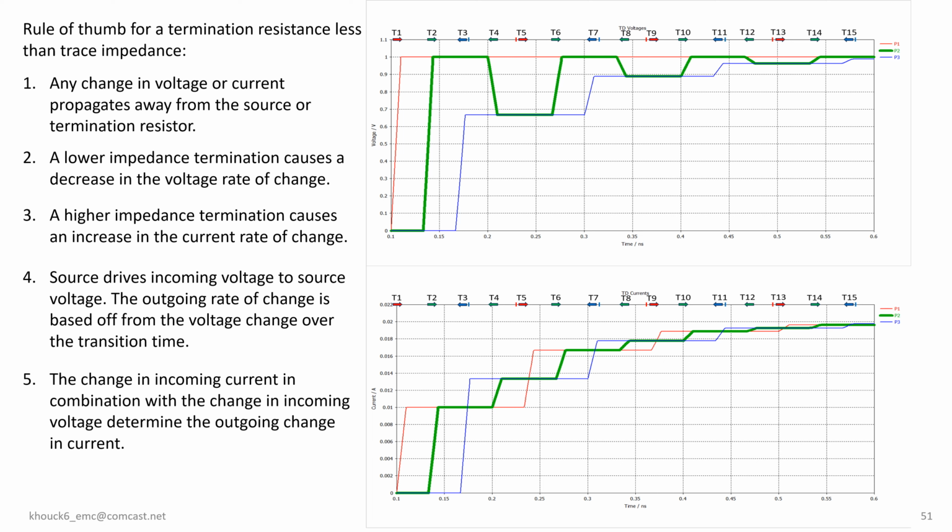At T5, Rule 4 is activated as the voltage undergoes a transition to match the drive voltage. Consequently, this voltage shift induces a change in current, which is influenced by the trace impedance. Simultaneously, in accordance with Rule 5, the incoming change in the magnetic wave combines to generate a faster rate of change. At T6, the changing field waves traverse the midpoint.